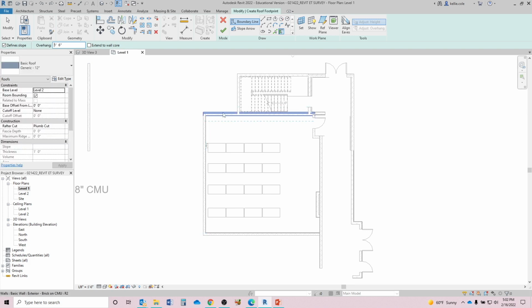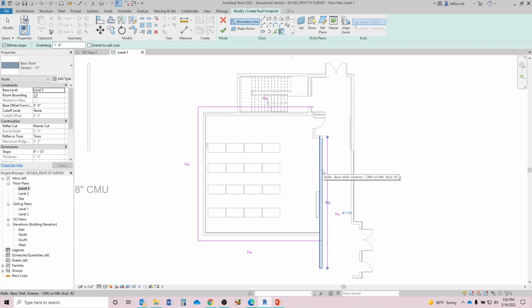Now look, when I hover over the wall, just like the offset command, it shows a dashed line. I want my dashed line to appear outside of the classroom wall. So I'm going to select each of those 4 walls and then use my trim tool and hit escape twice, T, R for trim, touch the parts of the walls I want to keep, same here.